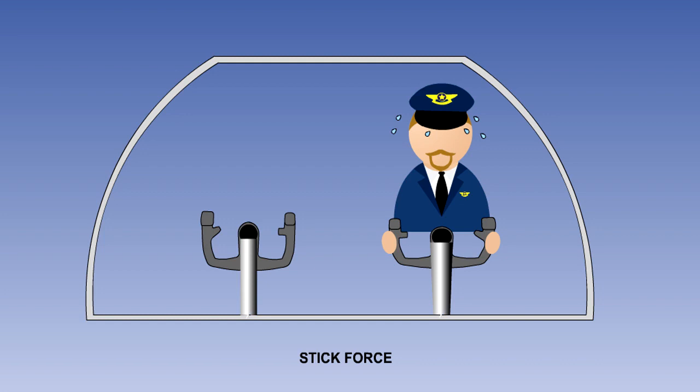If the pilot does need to move a control surface to maintain the balance of the aircraft, he will need to apply a force to the cockpit control to hold the surface in its deflected position. This is commonly known as stick force, irrespective of which control is being operated. This force may be reduced to zero, thereby reducing pilot fatigue, by operation of the trim controls.